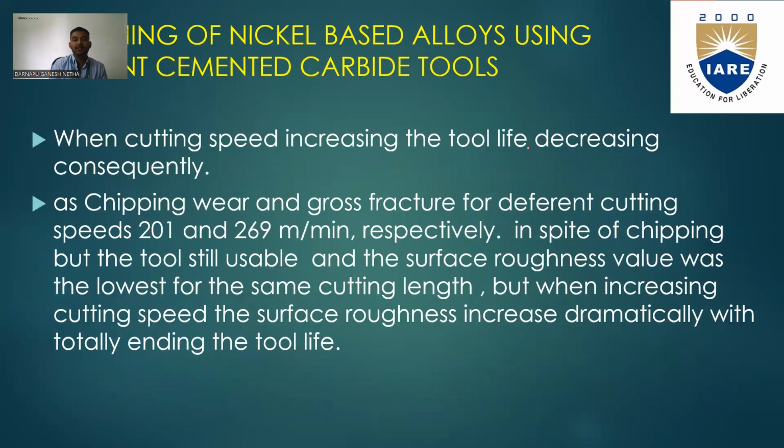When the cutting speed increases, the tool life consequently decreases. In the first slide we discussed that the cutting speed is inversely proportional to tool life. That means whenever the cutting speed increases, the tool life gradually decreases. In order to increase the tool life, it is better to go with a medium or low cutting speed. It is the best approach.